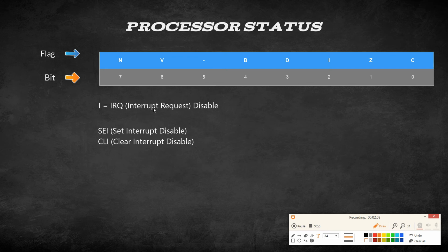So like I said before, an interrupt request can be sent by software or from hardware. Like the example I gave you before, somebody using the controller and pressing the up button on the computer, for whatever reason, is going to send an interrupt request because they think that's a bigger priority than what you have. But if you are programming and you have a part of the code that's the highest priority, you set it. So you type SEI for set interrupt disable, and when you're done with that part, CLI to clear interrupt disable.